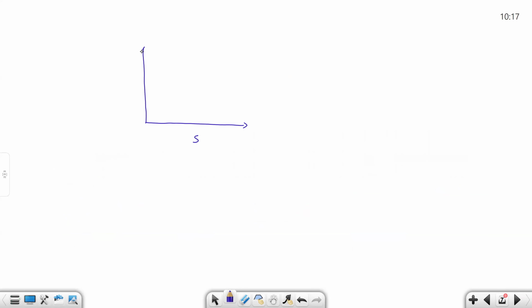So entropy versus the temperature. There will be 450 degree and 425 degree, because at 425 degree is what we want, then 400. So corresponding to that 400, you have an entropy value, and at 450 you have an entropy value. So this is the linear interpolation. This is your S2. This is what we want.